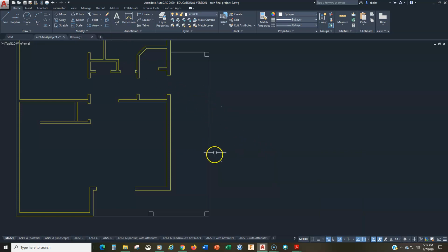So here's what we can do. Let's go to copy, and we'll window that. We're going to use the same technique with the object snap tracking. I'm going to position over here, and I'll tell you when I click. I'm going to click to grab that as my base point, and move it over here. And now what do I want to do? I want to grab that node and track it off right there. Boom. Grab that node and track it off.